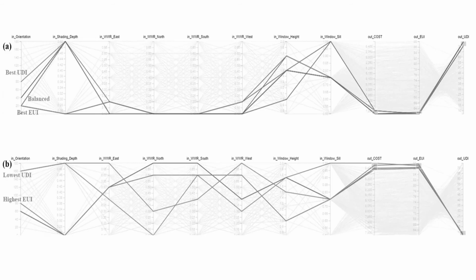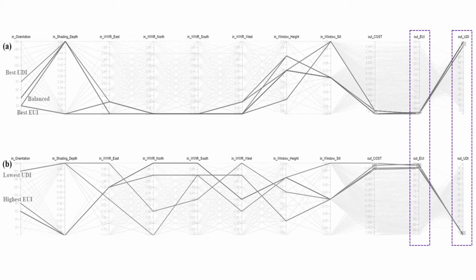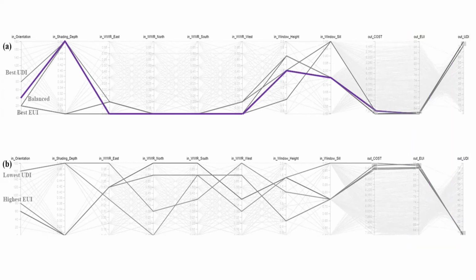We used a Pareto front algorithm for optimization. We considered useful daylight illuminance and energy use intensity as multiple fitness objectives. This process helped us to acquire the insights regarding the best possible options and impact of different design variables on the energy performance.